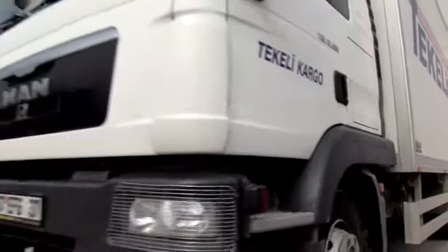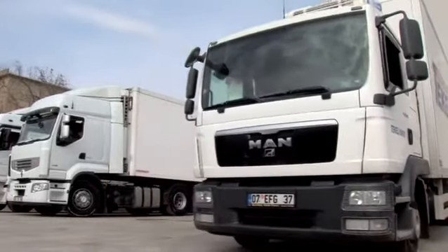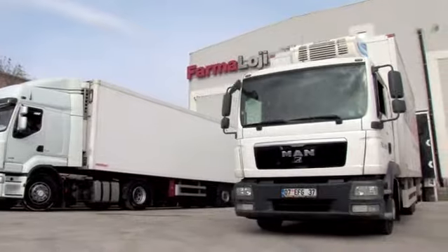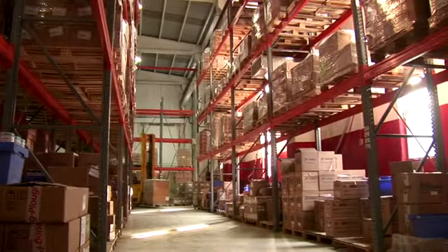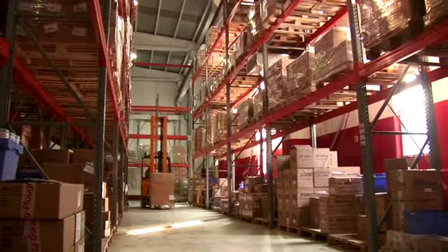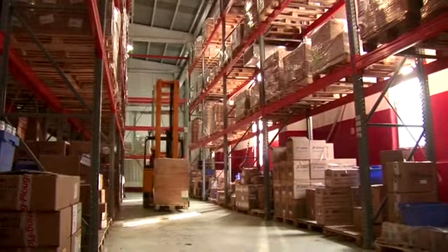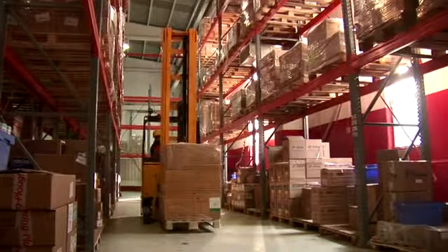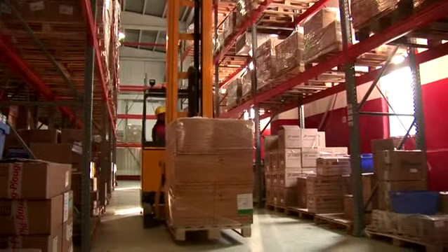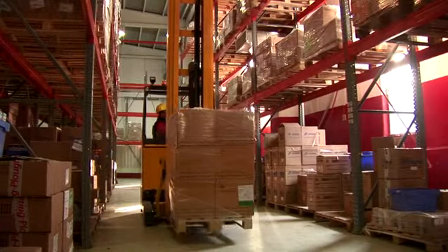We now turn to the question of site access. Larger facilities must be suitable for all the types of delivery vehicle that are used to supply that facility. So there's got to be safe access to and from the site, and adequate road widths and parking areas and turning areas within the site itself. In addition, if products are offloaded from vehicles using forklift trucks and other mechanical handling equipment, you need to be sure that the road surface is suitable for the type of equipment you're going to be using.